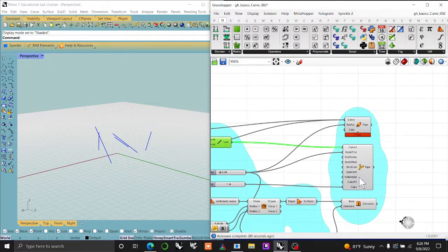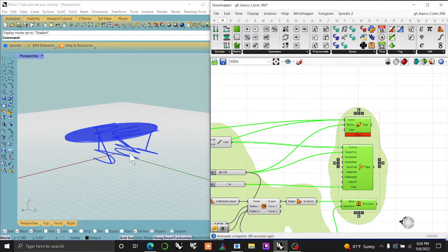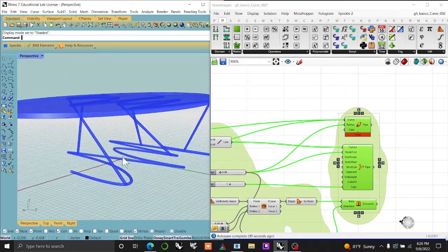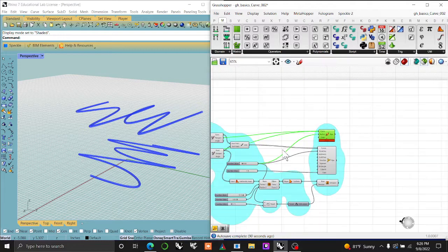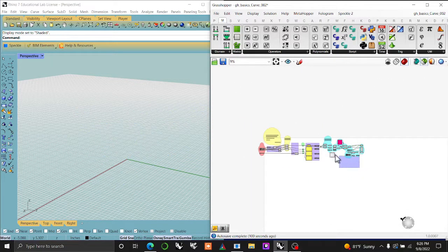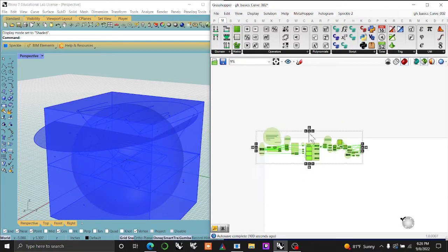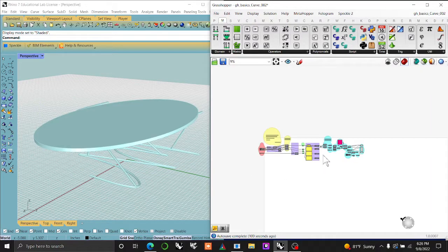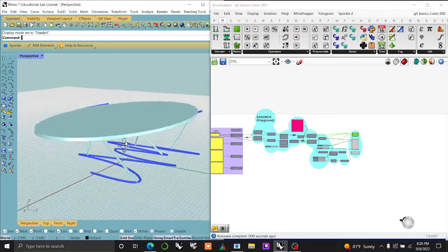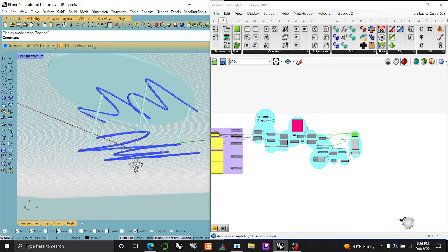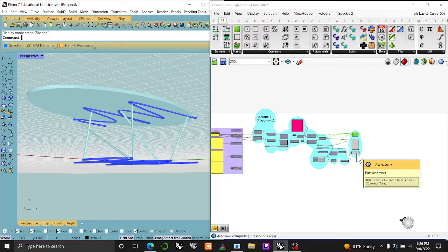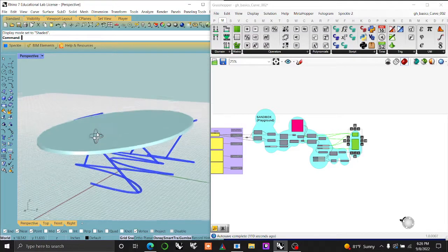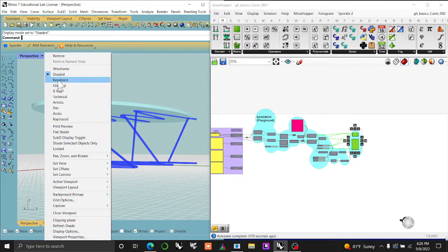So pretty easy stuff. Nice subdivision tools, pipe, you could use variable pipe, and aesthetically you can really just take a look at this and see what you like. So what I'm going to do is go back, grab everything but those final nodes, take preview off, put this so you see everything, and then select the one that I have. Nice little diagram, nice little shape. If you want to get into piping, it can be kind of fun. I'm going to grab the other pipes as well, and that's it. Not too hard to figure out.